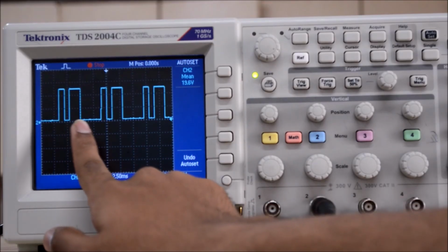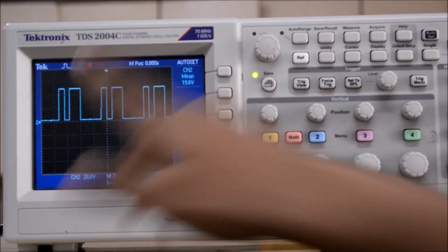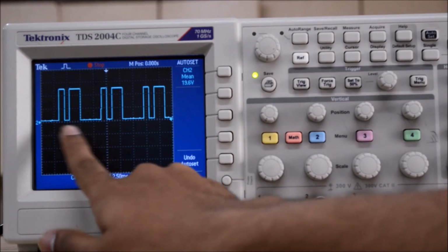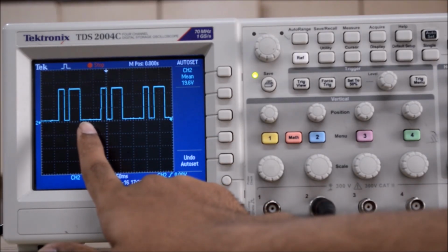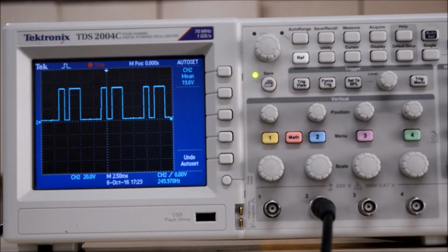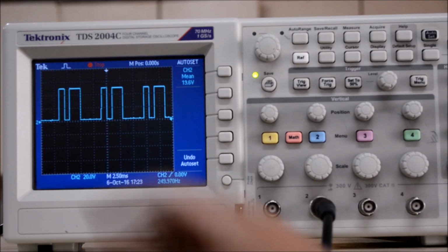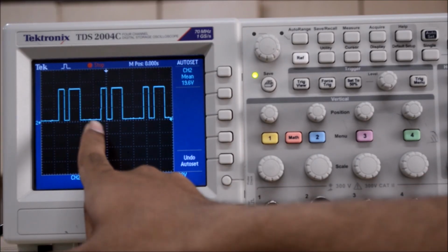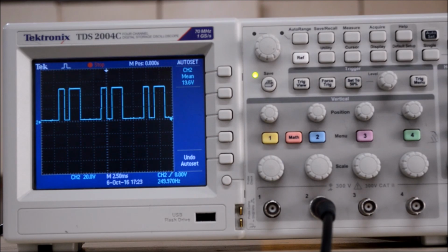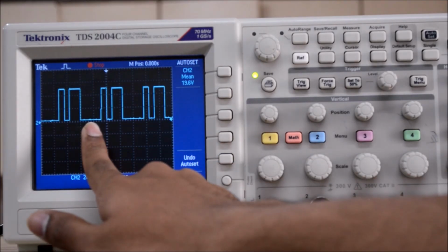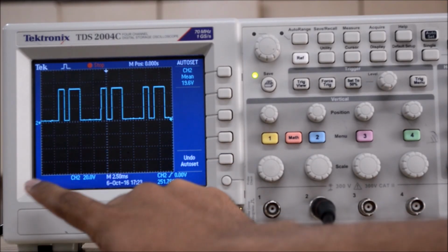It may happen that this signal may get inverted, that is the output of this receiver may get inverted. So you should do one thing: turn off the kit, wait for 10 to 15 seconds and then turn it on so that we can get the original signal. As I had mentioned of the OR gate, when we switch on the kit, the receiver knows that the first incoming bit will be bit 1. So it verifies that the output is original modulating signal used at the transmitter side.